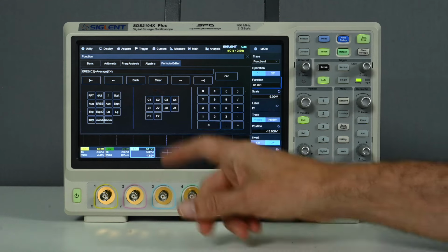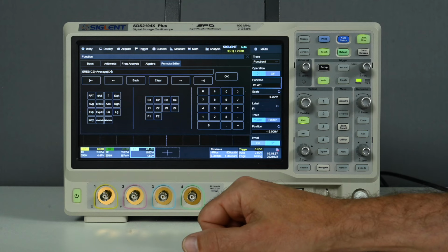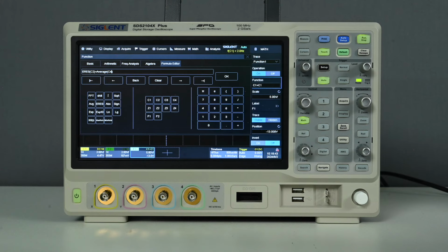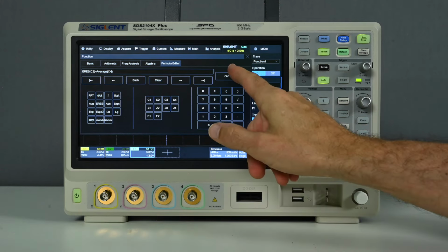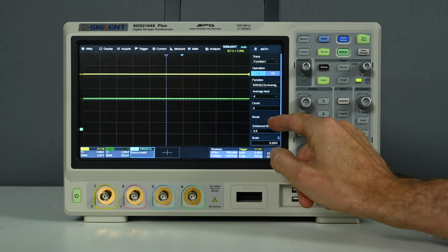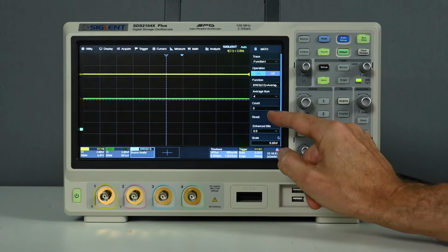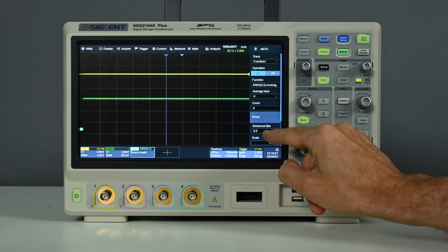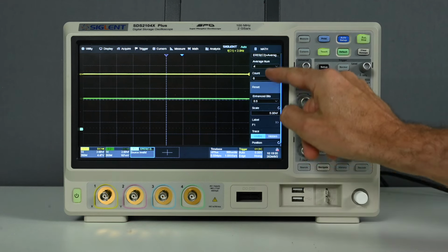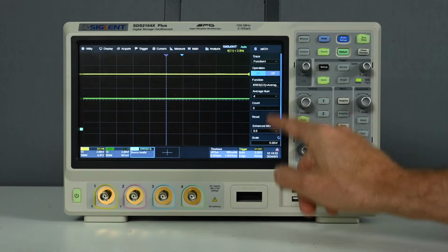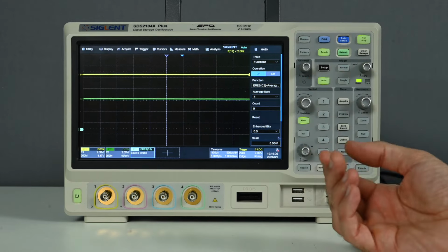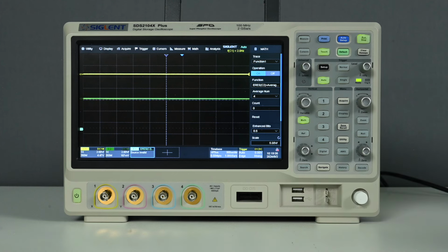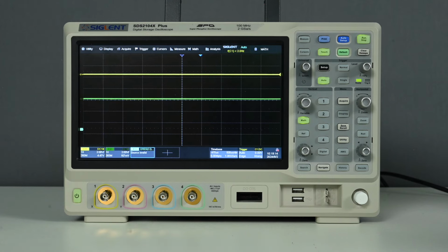So you don't get to select that here as you do in some other devices, as I'll show you in a moment in the PicoScope. But what actually happens, you just make the formula, you don't look at any of that, you start to execute the formula, and then here in the menu you get the average numbering and the enhanced bit. So for all the parts of the formula, and there will be more here if you add more things that need parameters, this is added here in the menu after you actually activated the math function. I only found out about this after a while. I was really struggling where I should be setting my parameters.